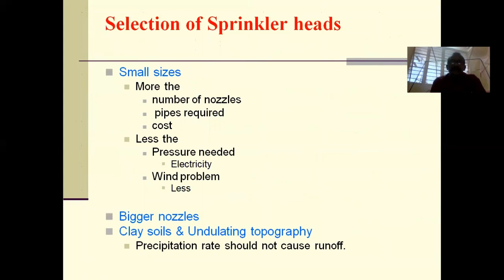Now let us see how the sprinkler heads can be selected, and what are all the factors that should be considered when we select sprinkler heads. When we make use of small sizes of sprinklers, we may have to use more number of nozzles. And when we use more number of nozzles, we need to have more pipes. So the cost of installing small size sprinklers with more pipes will be more. So the fixed cost of small size nozzles usage will be more.